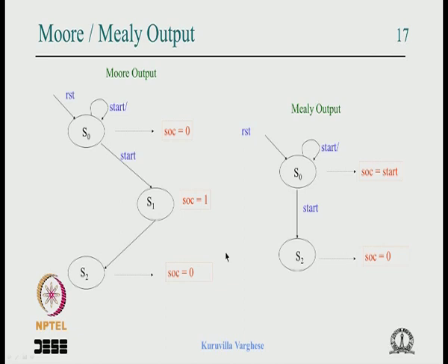If the number of flip flops is less, maybe the next state logic, because it is a function of the present state and input, becomes smaller in area, and the output logic, which is a decode of the present state and input, becomes smaller too. So the area can become small, the state machine can be clocked at high frequency, it occupies less area, reduces power dissipation and so on.